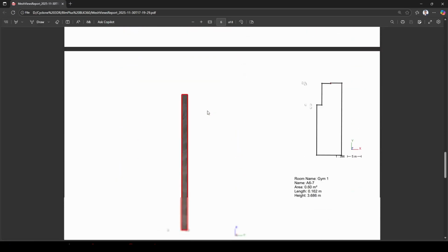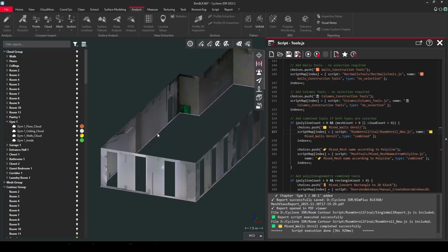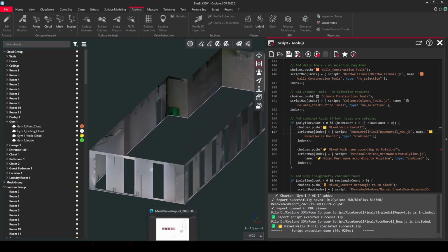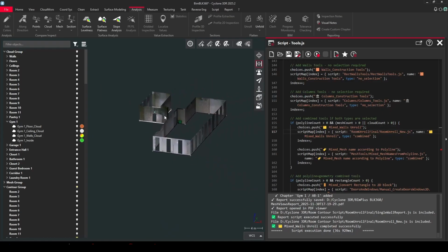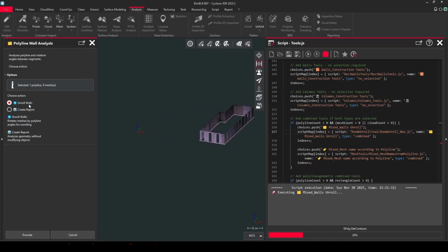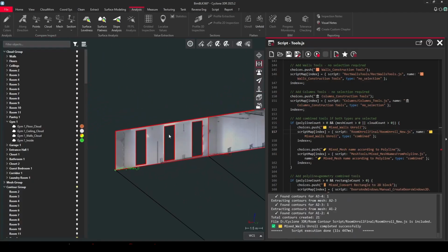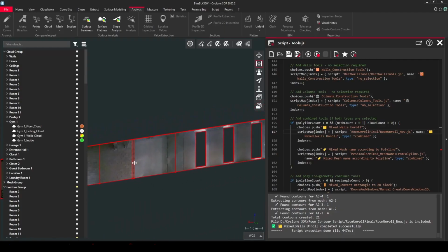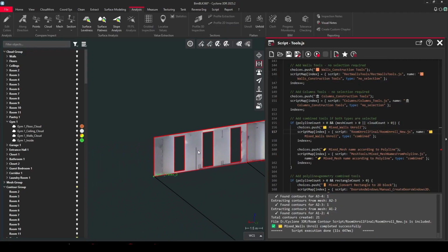These views generated just as a preview. You can generate better views manually in 3D by using standard 3D tool. Before running this tool, I recommend you to color this line into black color to be sure that it will be visible here in the top view. And second option allows you to unfold this, select the mesh and the polyline, run the same tool, walls unroll, and here select Unroll Walls. In that case, you will see that here directly in 3DR all walls will be unrolled, and you can work with them separately or measure manually everything or generate views manually.